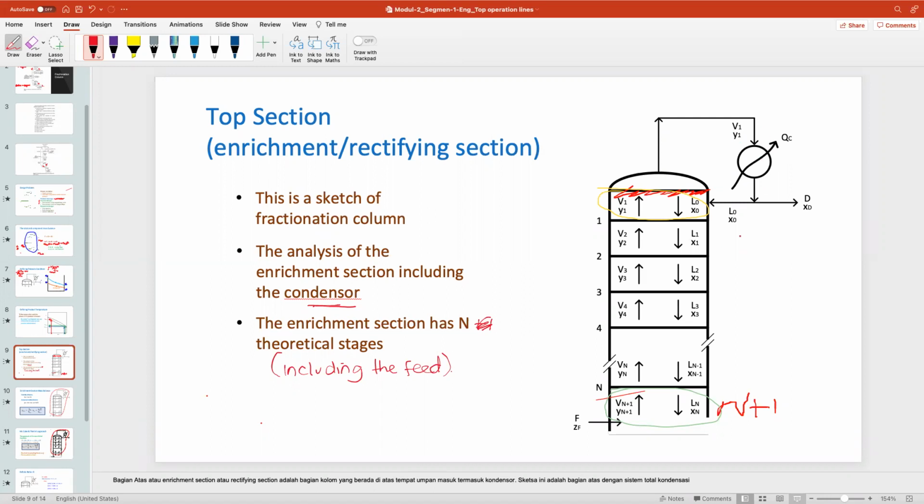But if I have another condenser, which I would call a partial condenser, like this, I vaporize some of them and I also get the liquid. Sorry, I need to delete this. Okay, but I take the product as a vapor again, as a distillate. So I get the product as a vapor and the reflux as a liquid.